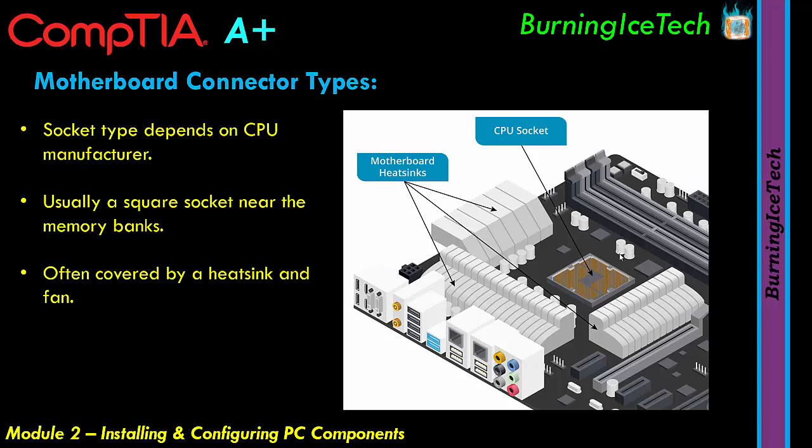Once you've got the CPU in there, there's normally a heat sink you need to put on top of the CPU. So you're first going to apply a little heat paste, which is also known as thermal compound, on the CPU. Then you put your little fan on top of that heat sink, and that's just going to cool down the heat sink. But around the CPU, there are no heat sinks. Towards the bottom half of the motherboard, which you can't see in this picture, you're going to find a heat sink possibly on the north bridge, and in some cases even on the south bridge, if you guys know where that is. But around the CPU, you're not really going to find heat sinks that commonly, not like in this picture. Those are very, very rare. Not something you're going to see.